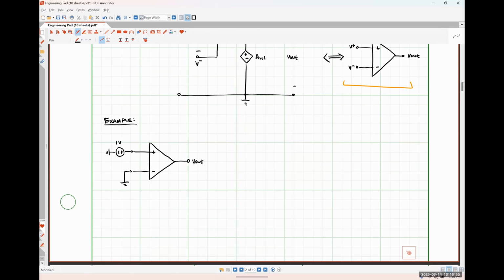Now, as we talked about at the very beginning of class, amplifiers are active devices, meaning that they require external power. So I'm going to make a note of that by adding a positive supply voltage terminal here, which I'm going to say is 10 volts, and a negative supply voltage here, which is negative 10 volts, right? So that's us applying power to this device.